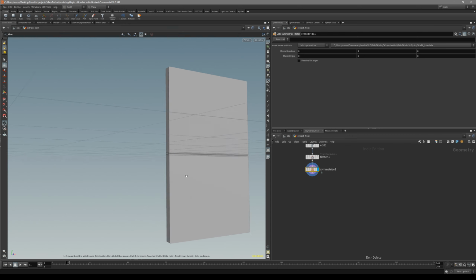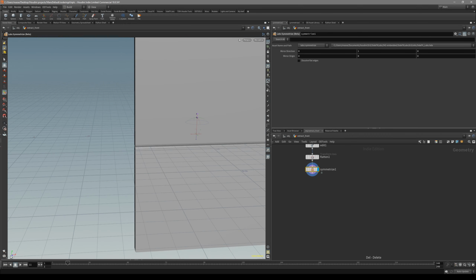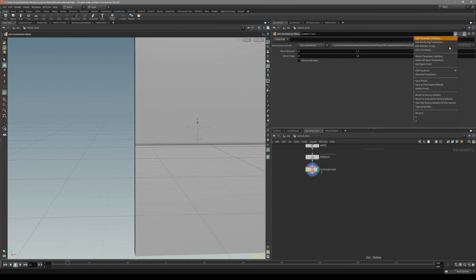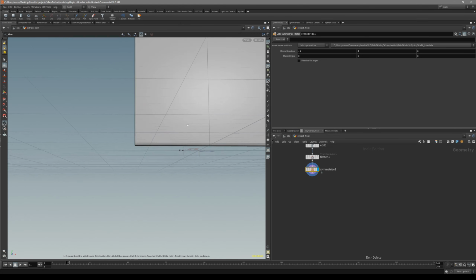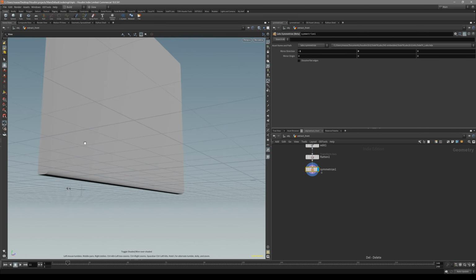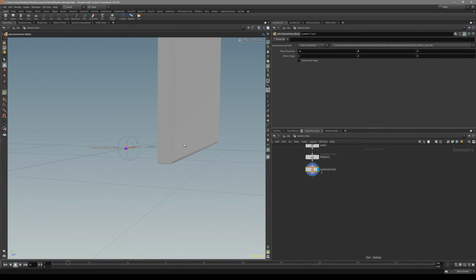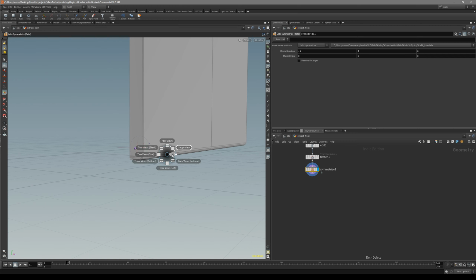What I have done is create a couple of presets. I know that I have to mirror on the X axis, so in my preset I'm going to press mirror X. You can see I have now mirrored the X axis on this side, and there's even a cool option like dissolve flat edges, but now I'm not going to use it. By default you kind of have to do two operations: you have to clip it and then you have to mirror it.